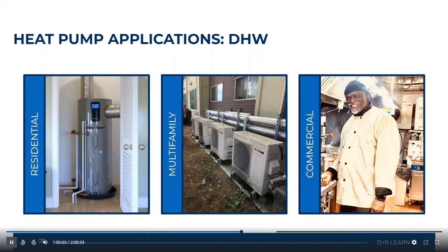I just want to touch on the heat pump system that you see in the commercial kitchen and the multifamily, which is the Sanden SANCO2 heat pump. Just some specs on that system for those who are interested. The hot water production is down to negative 20 degrees Fahrenheit ambient temperature. So you can have hot water production down to negative 20 degrees Fahrenheit utilizing the SANCO2 heat pump systems, up to 175 degrees of hot water temperature delivered.